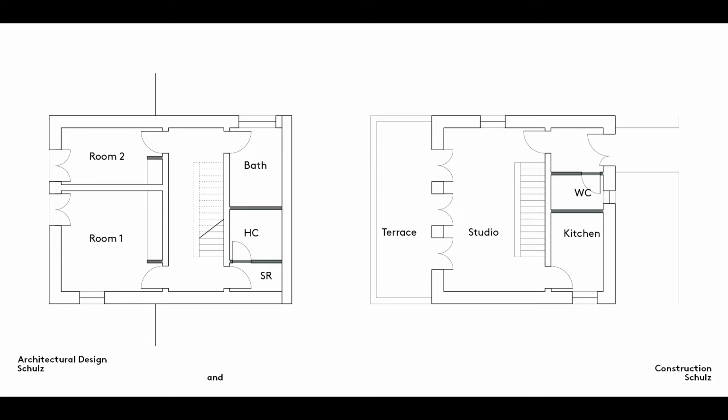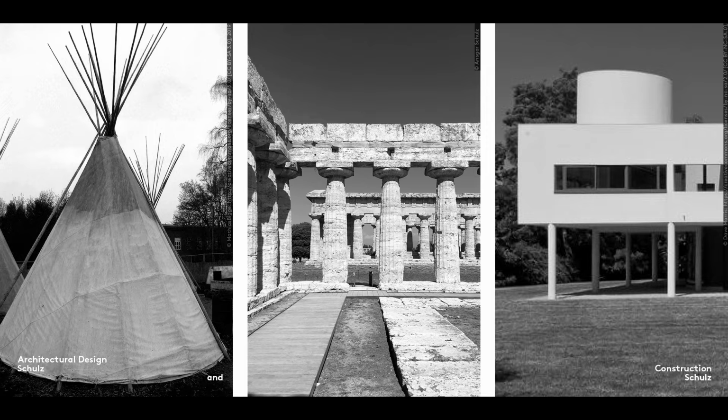This one shows the non-load-bearing walls of a house. They can be thinner because they don't have to support the weight of the floor above. Since the soundproofing requirements for the rooms on either side of the walls are also relatively low, they can be built using half-brick masonry. Now let's take a look at supports.